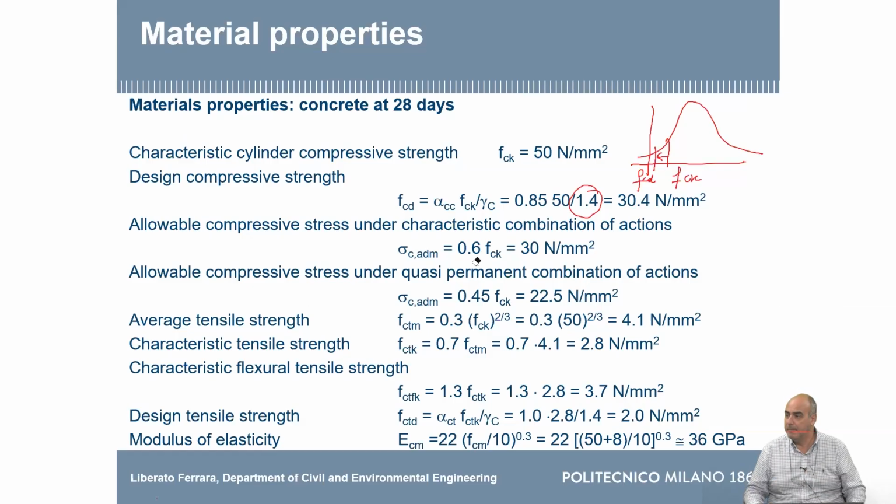It's the rare one, yeah. Rare one, yeah. Without load factors, they are 1. Whereas in the quasi-permanent, you have load factor 1 for the dead loads, and this 0.3, 0.5, 1, it depends. It's not a load factor, it's a combination factor, which gives you the percentage of that load which you can consider as quasi-permanent, as if it was permanent.